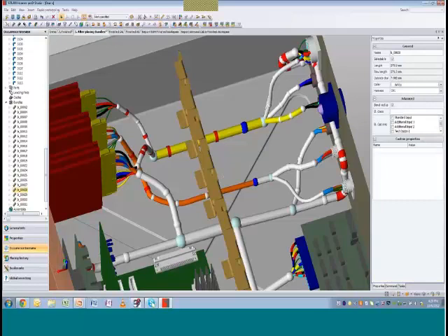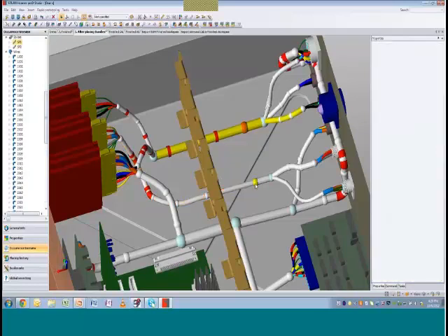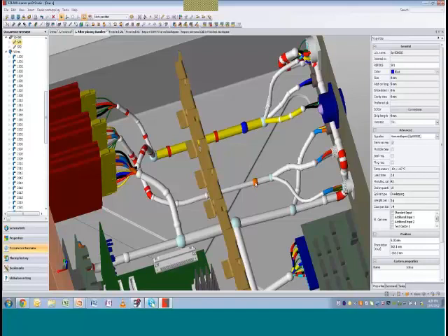You'll also notice these little blue indicators here. These are splices. So there may be a single wire coming through the harness that ends up being spliced into 2 separate areas or 2 separate locations, or even more. And here we're just indicating a splice. And again, that is part of our bill of material as well. So it's going to keep track of that splice and also the part information for that as well.